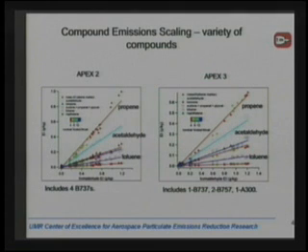When we're over in this region, we're looking at the low powers. As we go up in power, we go down here. But you can see even for a low power condition, we have significant scatter because of the thermal effect that I was talking about. The ambient temperature was having an impact. But when we collapse that or look at it with respect to formaldehyde, we get a very nice correlation. So the engine is actually very reproducible. Our measurements are very reproducible. And all these hydrocarbons go up and down together.